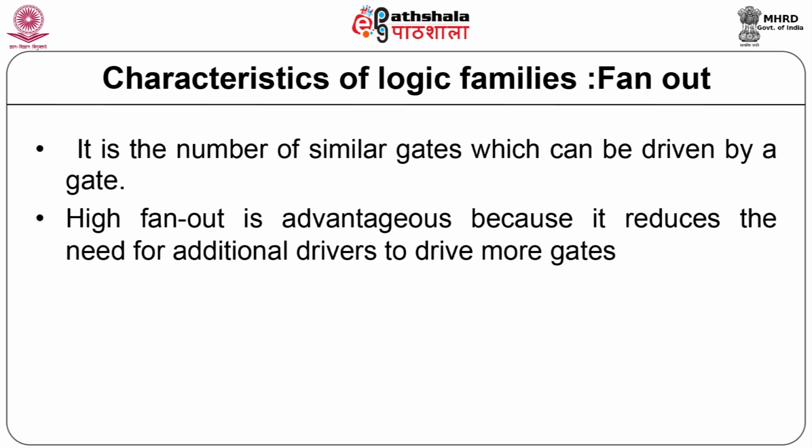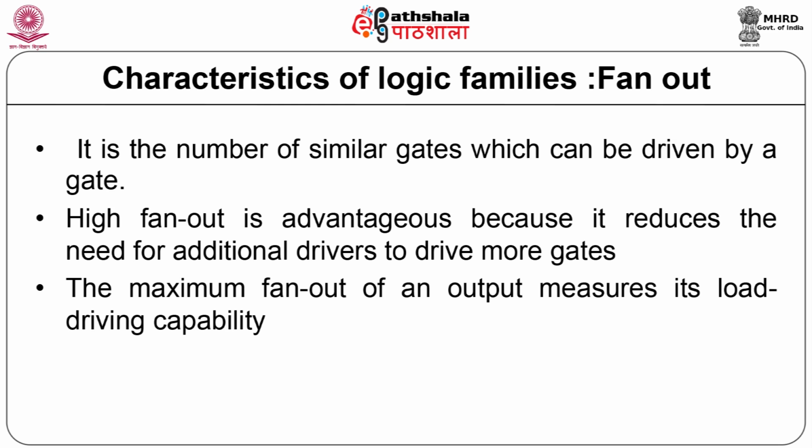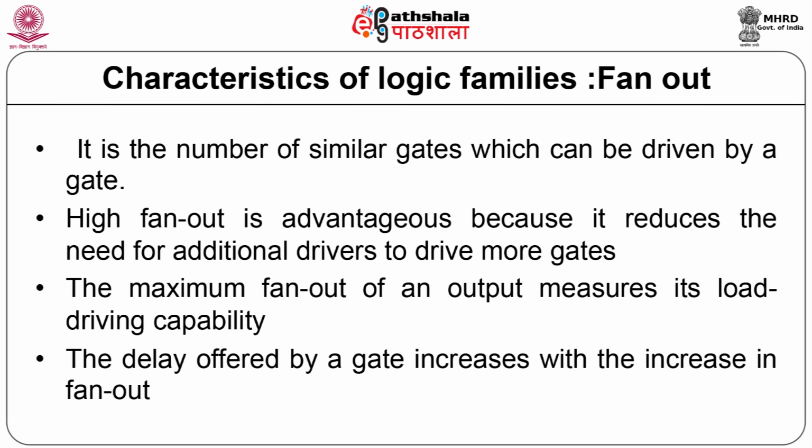High fan out is advantageous because it reduces the need for additional drivers to drive more gates. The maximum fan out of an output measures its load driving capability. The delay offered by a gate increases with the increase in fan out.